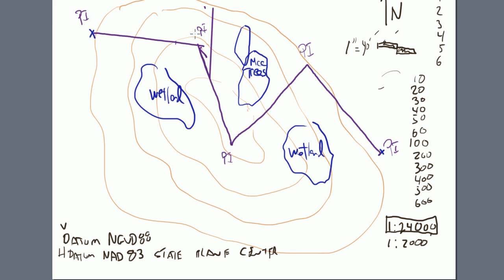You can realistically, when you're learning the horizontal curve calculations, come back and actually figure out your radius is what you want, and sketch in your curves here relatively close per se. And you have now a PC, a PT, a PC, a PT: a point of curvature, a point of tangency, a point of curvature, a point of tangency. Right, you have each of these.